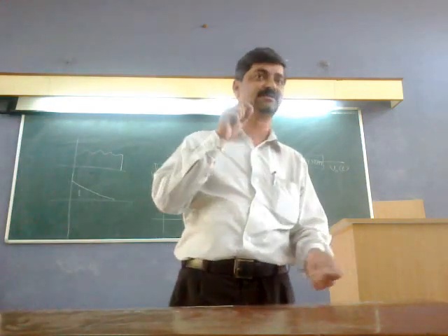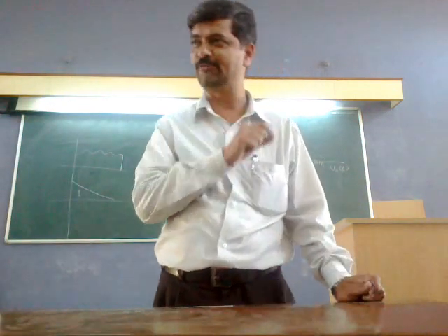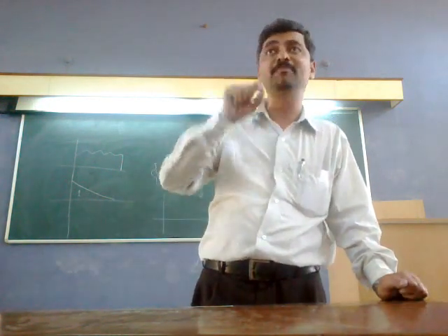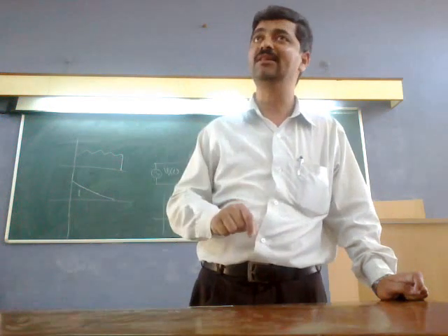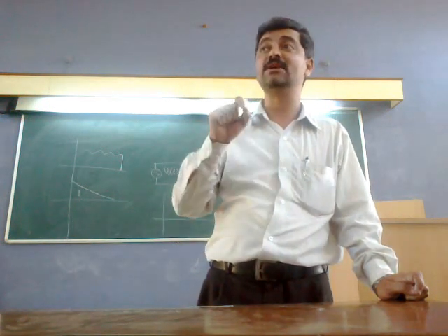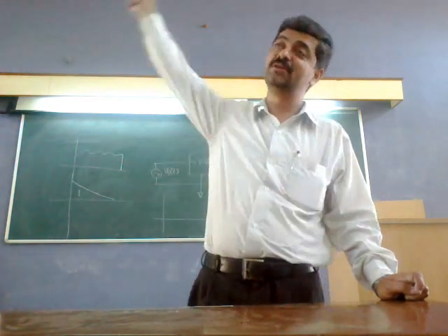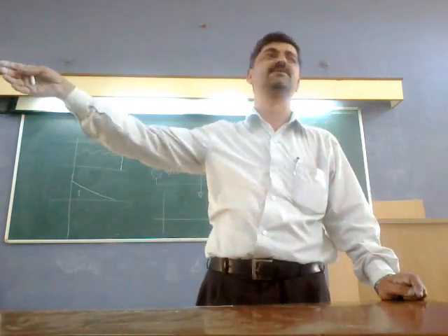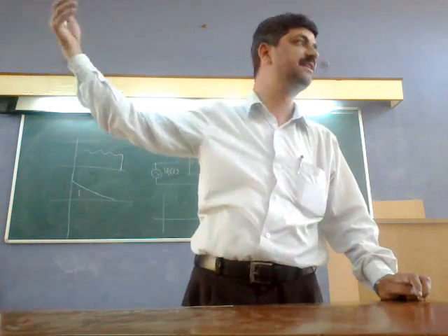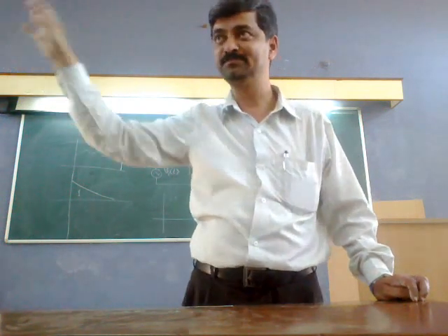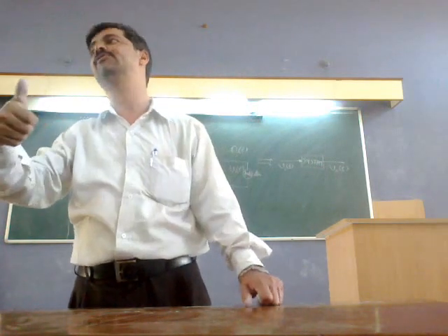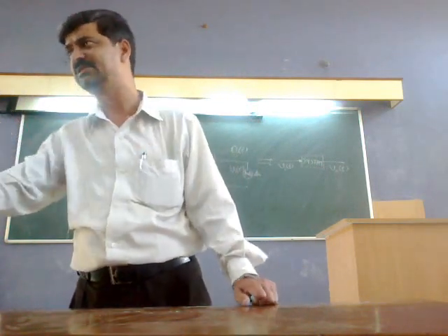The output of a system at any point of time is the weighted sum of all previous inputs. When I say all previous, then it should go till minus infinity. But obviously, again, we should be practical: after some time the weights are highly negligible, so I can ignore them. So I just rephrase my word of average. There is no need of division now.